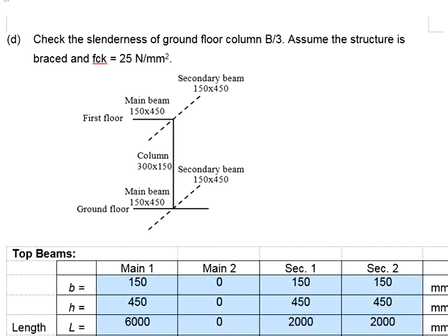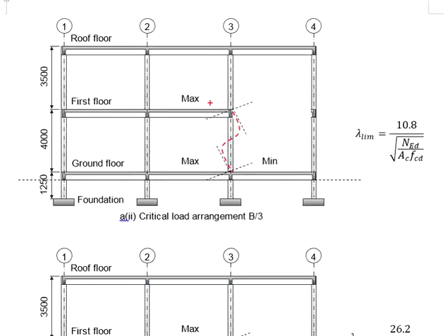When the moment is relatively small compared to the capacity of the column, or more specifically to the capacity of the connections, you will expect little deformation of the connections, so the deformations of the columns may not be as critical as this.